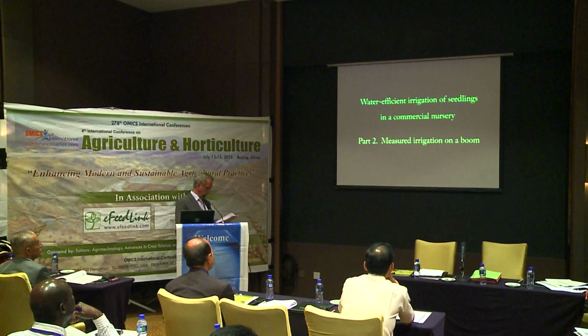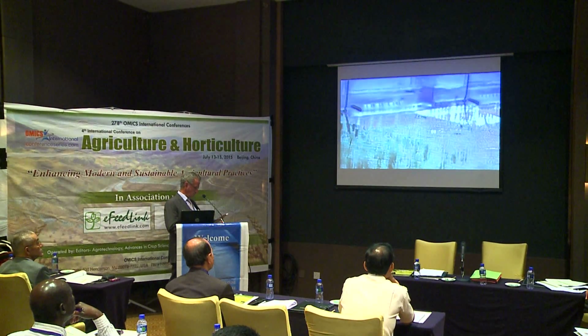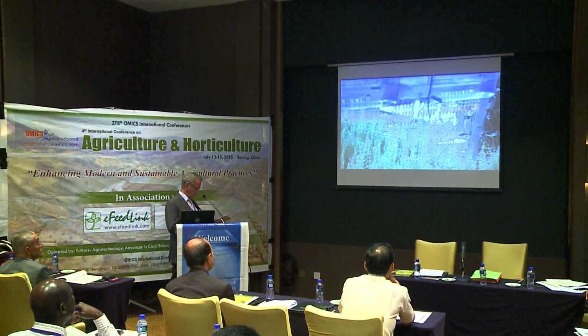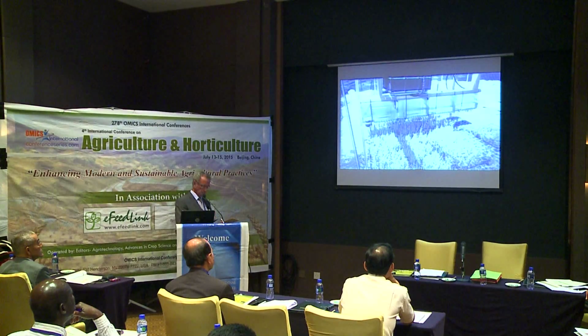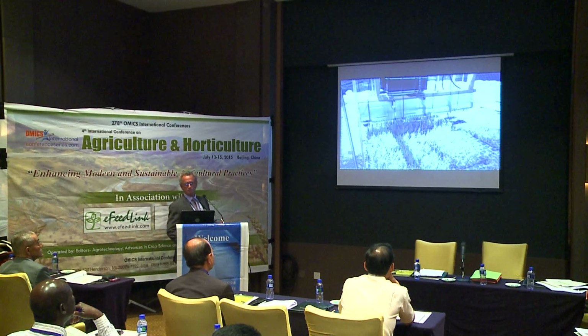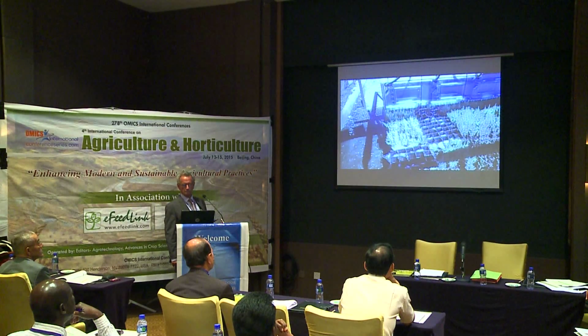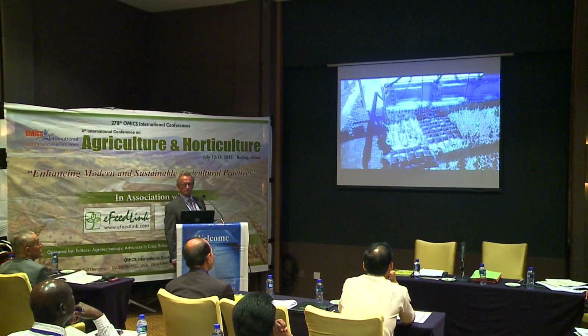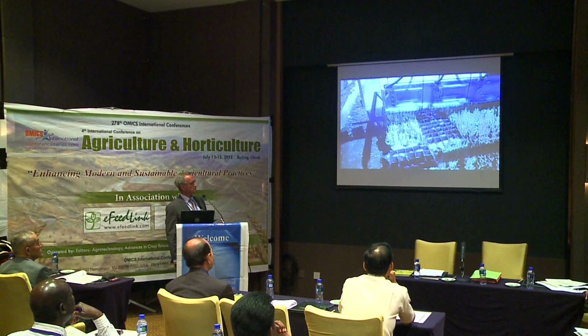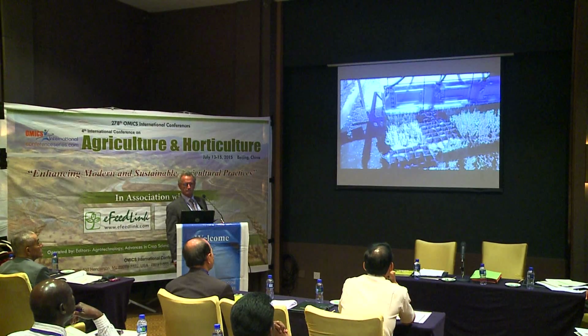You decide in advance how much water each seedling requires during the irrigation event, and measured irrigation will automatically measure the prescribed volume of water for each seedling. One of the challenges in the nursery is the scheduling of the controller to automatically water your plants without wasting too much water. With measured irrigation, scheduling is very simple. The irrigation frequency is controlled by the prevailing weather conditions.